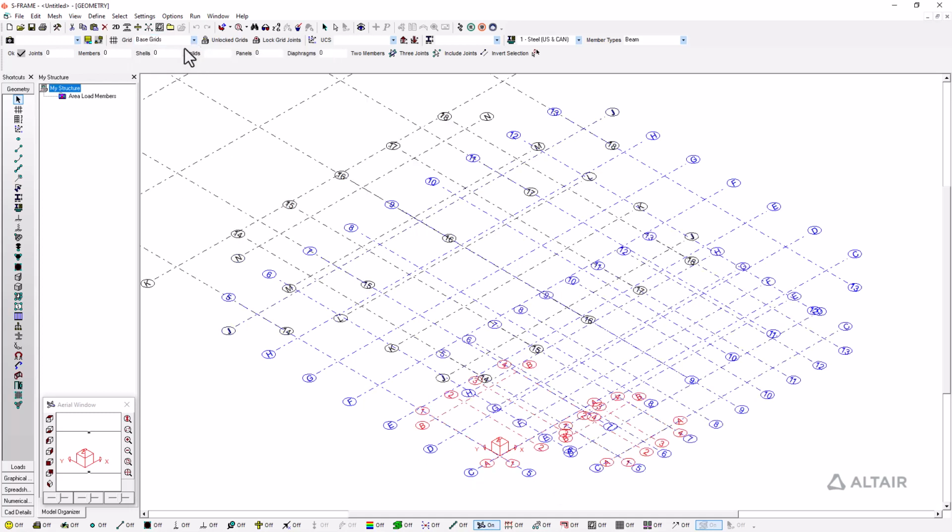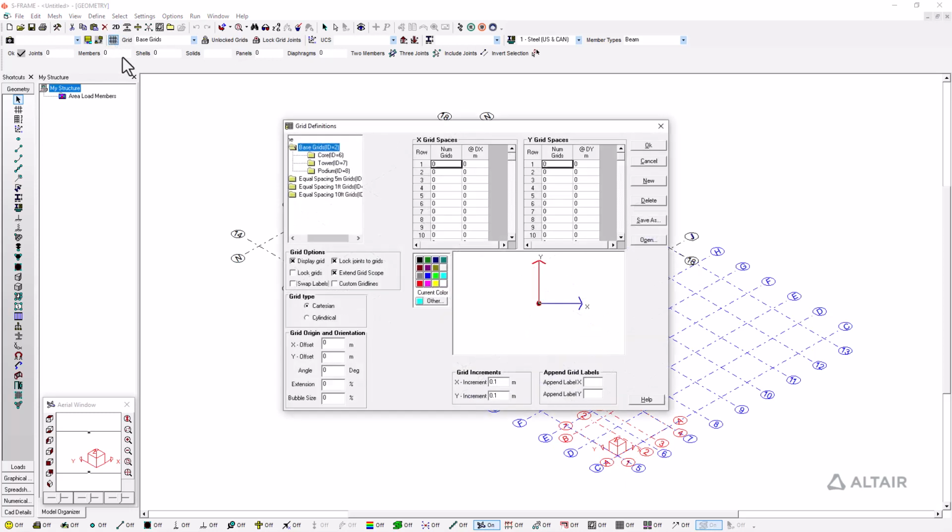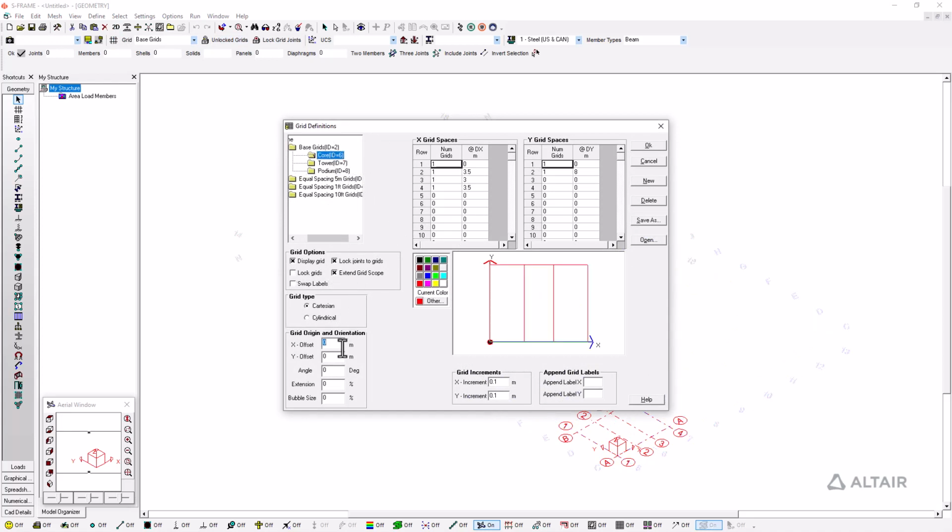And now if I look at my base grids folder where they're all right next to each other, it becomes pretty apparent to me that I don't really want my core grid to be at the corner of my tower. So I can reposition that as well. What I can do is go back into this Edit Grids dialog, and go to the core grid, and say, you know what, this current position isn't working for me. I want it to be kind of centered on my structure.